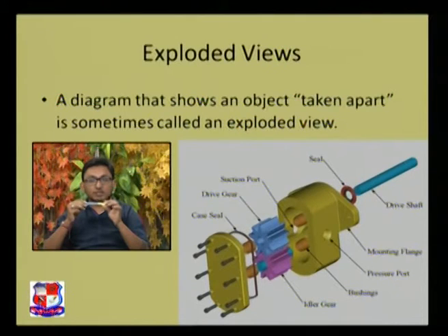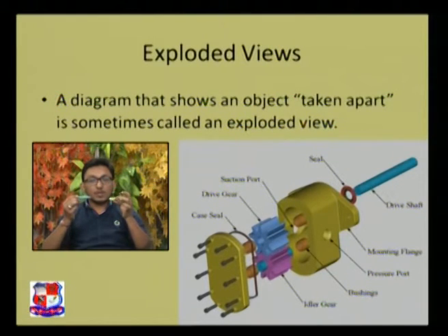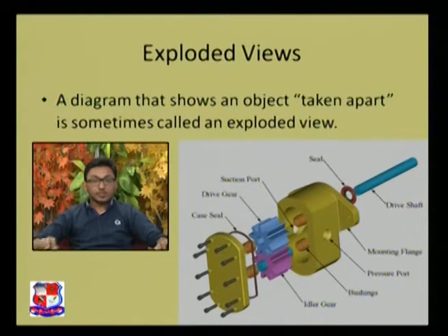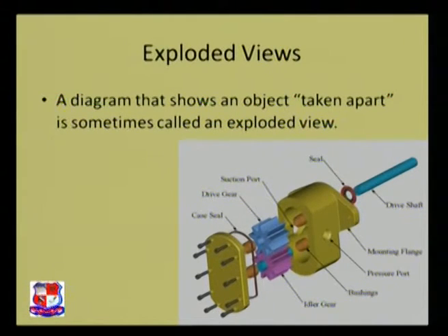Now I need to explode it to show how these two parts look when they are not together. So I will just explode them like this: this is the cover cap of the sketch pen and this is the main sketch pen. So it looks like this. When we are doing any sort of exploded view, it will be on the same axis only, and it can be assembled once more. So these kinds of exploded views can be generated for any sort of assembly.